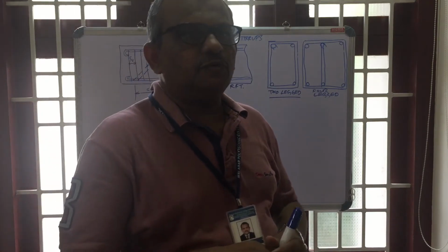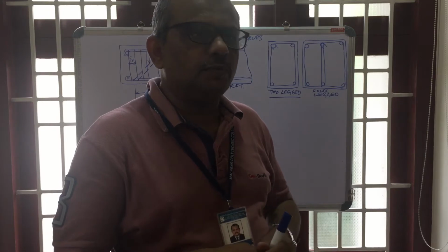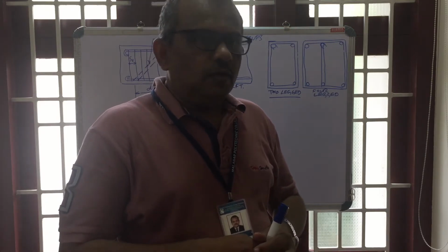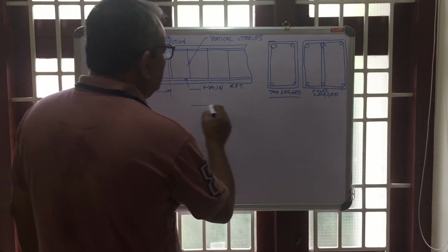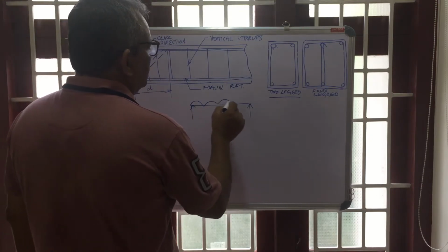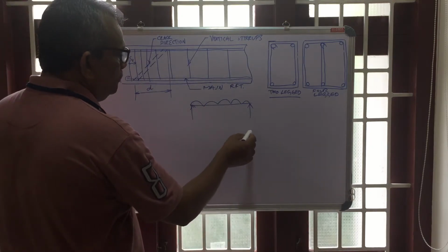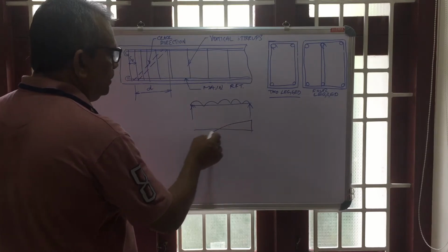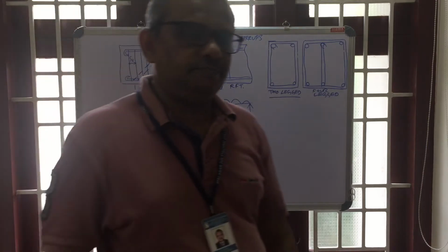So you should know first of all what we design shear reinforcement for, or what is the importance of the design of shear reinforcement. We already studied in our theory of structures that in a simply supported beam carrying UD loads, the maximum shear force will be at the two supports and 0 at the middle or at the center, right?